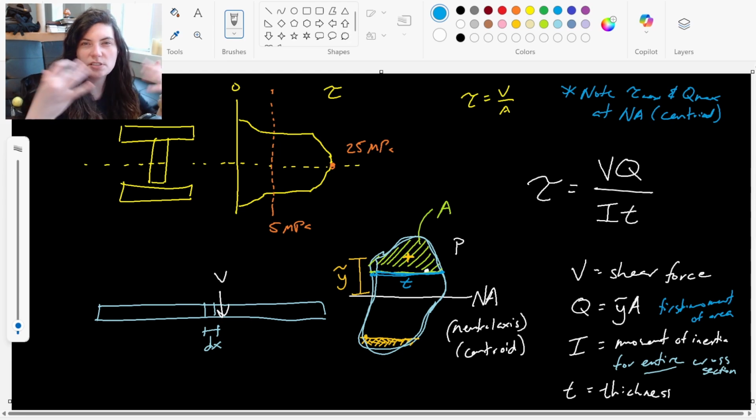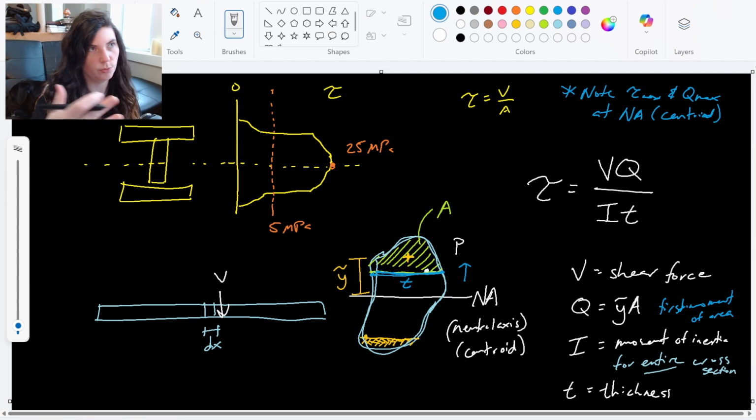So again, to sum all of this up, there's a shear stress on the surface of the cross-sectional area when we make that cut, and it is equal and opposite through the beam. So when we find the exact shear stress at this cross-section here, it's the same one that's going back through the beam, being transferred to any glue or bolts or nails that may be through that cross-section.